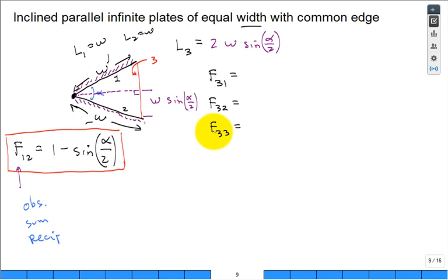There you go. 3 to 1 is going to be 0.5. Okay, 3 to 1, you took the hard one, is 0.5. Okay, staying with the front row, somebody give me the easy of these 3 view factors. There's only 2 left now. 3 to 3 is 0. How did you get that? Use your brain. It's a flat surface, neither convex nor concave.